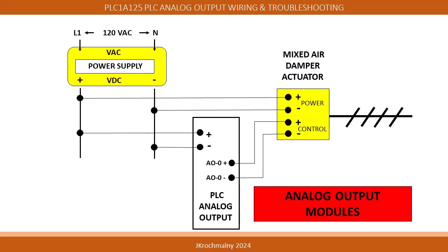As we may remember, digital logic involves 2 and only 2 conditions. Something is either on or off. Analog logic involves actual values. Something is closed, a percentage open, or fully open. In the case of this example, the mixed air damper actuator can be adjusted to be fully closed, 35% open, 75% open, or 100% open. These represent analog logic examples.